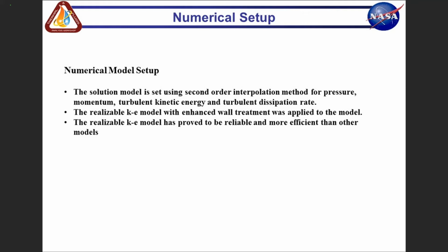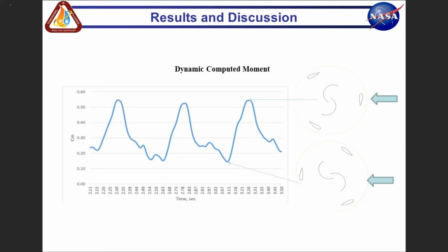In the simulation model we used the second order interpolation method for our solutions, and the k-epsilon model with enhanced wall treatment was applied. The k-epsilon model has proved to be reliable and more efficient than other models that we could use.